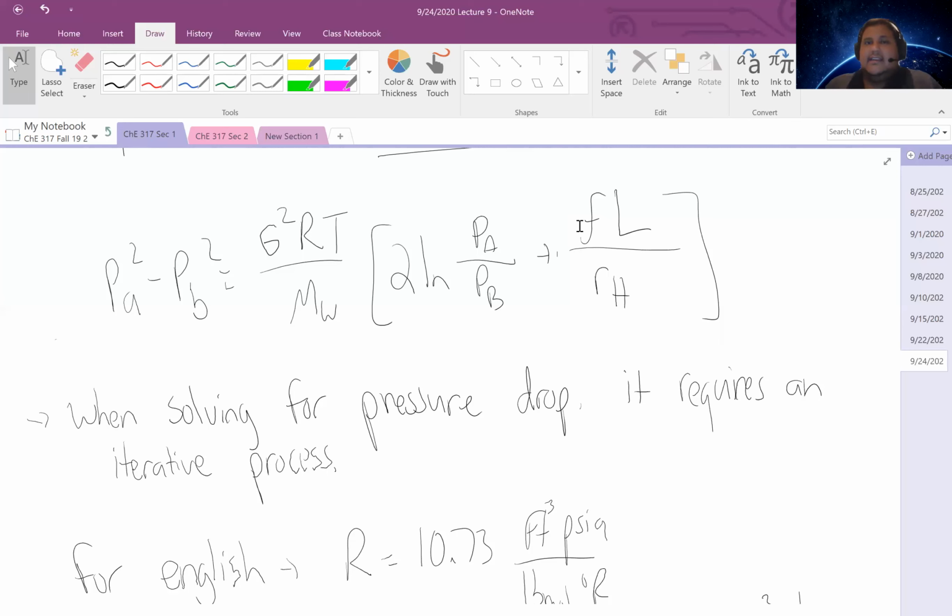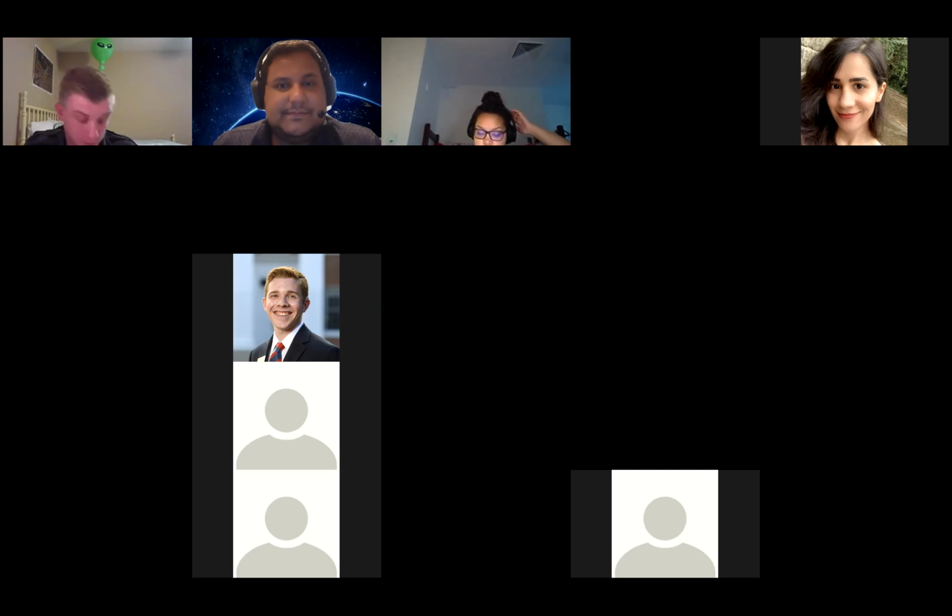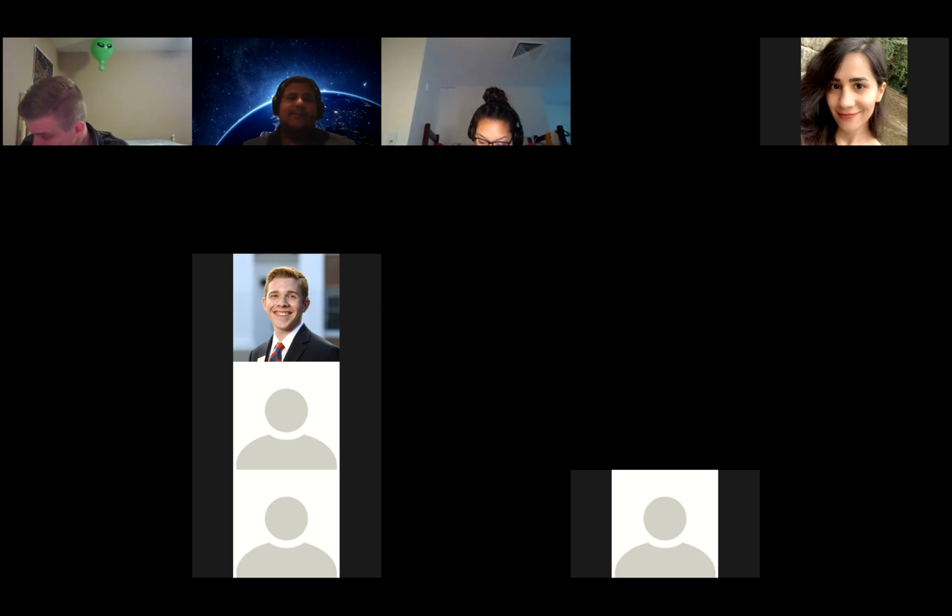So any other questions or things of consideration? For pressure drop, are we finding the difference between point A and point B, or are we finding the amount at point B? Most times you're looking at the difference. Okay, just checking. However, keep in mind for the expression in 6.49, it's the difference of the squares. And so it can get a little tricky depending on what you're doing and with your units, because once again, if you start jumping into English, it can get a little hairy.